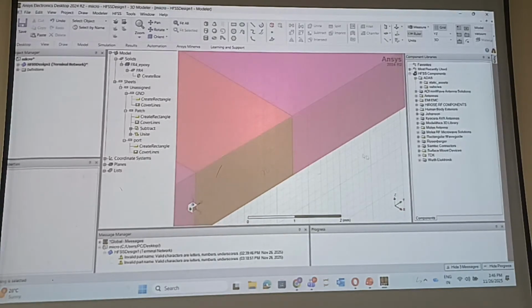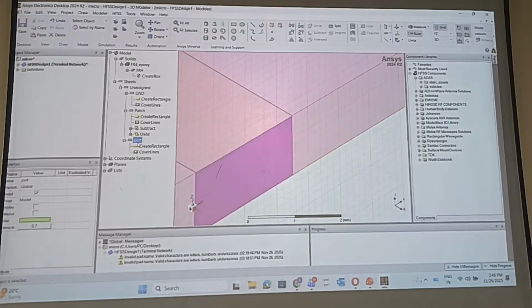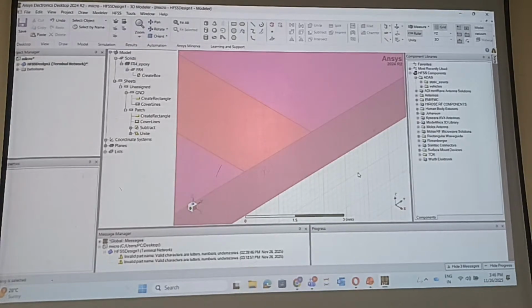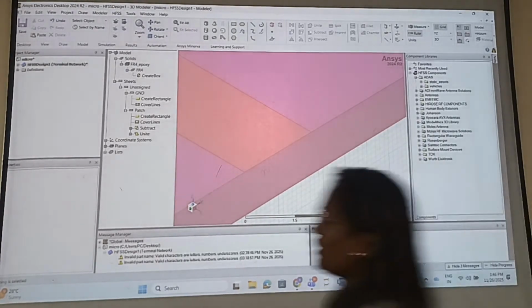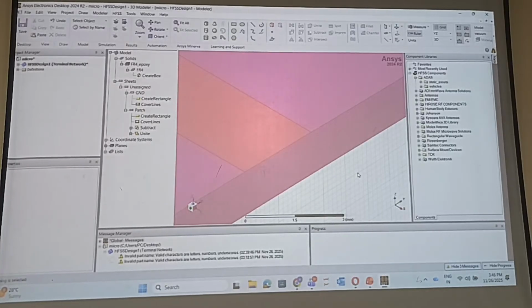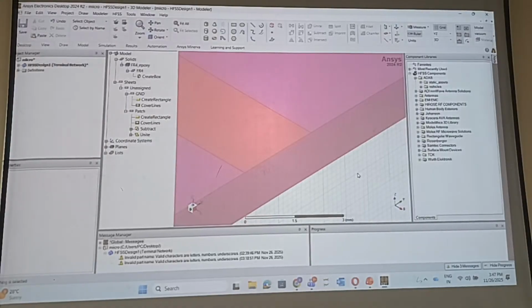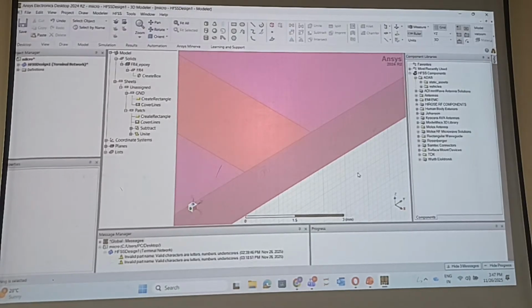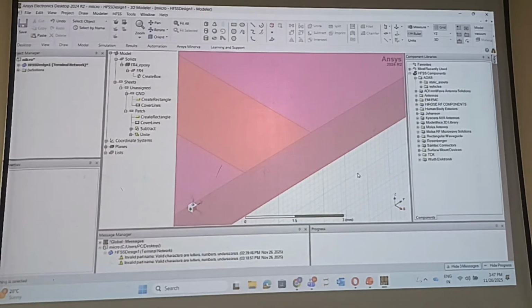Generally what we have to do, I just delete my code and once again I'll repeat. So you have to consider exactly these 2 points, draw one line and then drag to the bottom. So we have to create a rectangle shape over here so that the connector can be put over here when we are doing fabrication. So that's how we have the exciting port here.